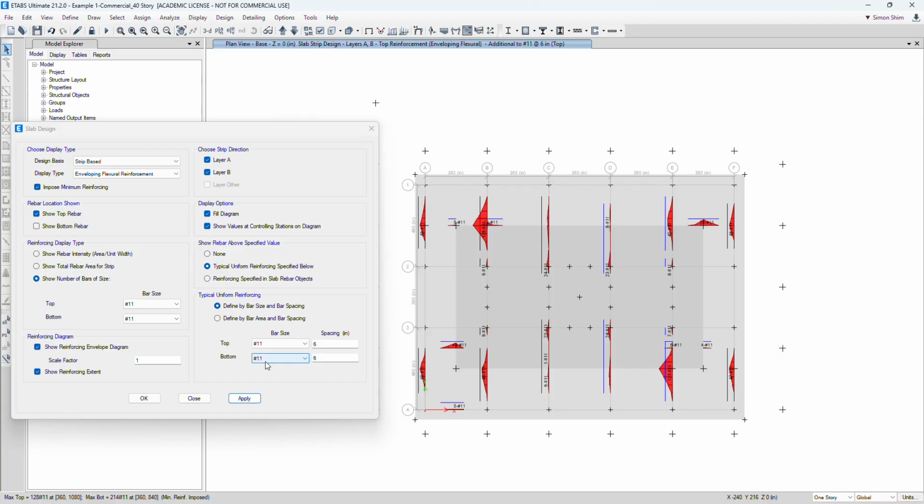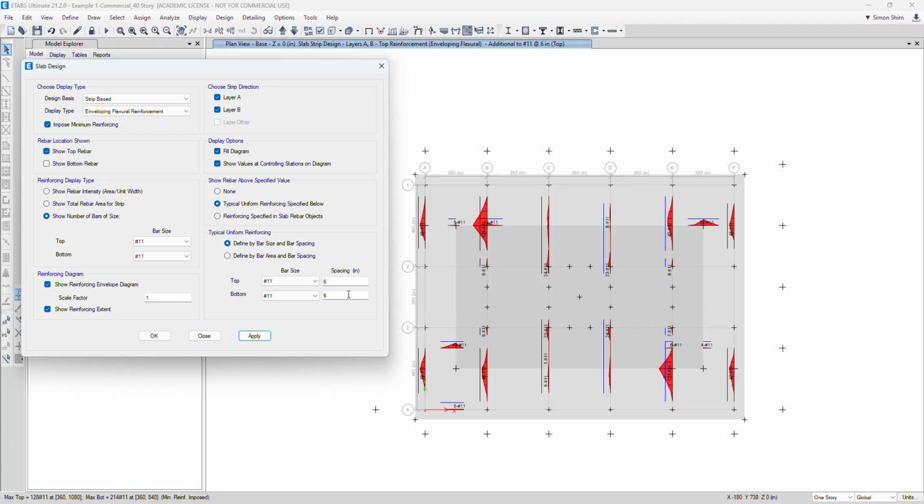So you could just bundle it. You could use 2 bars side by side, bundled, and you can use 12 inch on center as well. But because the scale of the mat is humongous, and most likely, just by looking at this, we need multiple layers. It's not going to be one layer. It may be two, three layers of bottom bar in X direction and Y direction. You could think of it based upon the intensity of rebar. Okay, so I'm going to